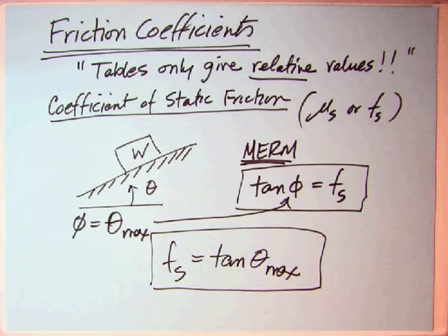We had a problem on a job one time where we needed to know the friction coefficient of a brake pad for using as a clutch to protect the transmission. Called the company. Well, they basically hung up on us. So we took the brake pad, put it on a piece of steel, did this experiment, and came up with a value that was right on.